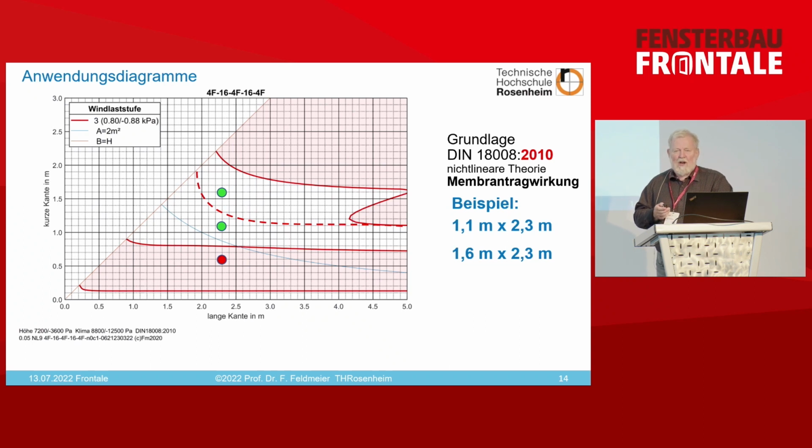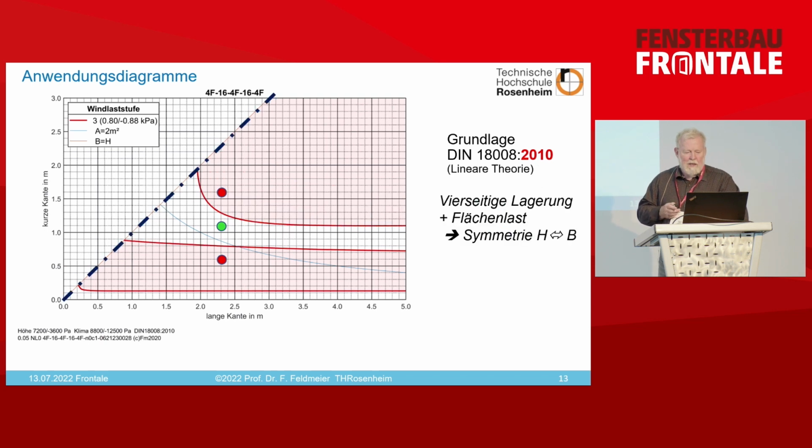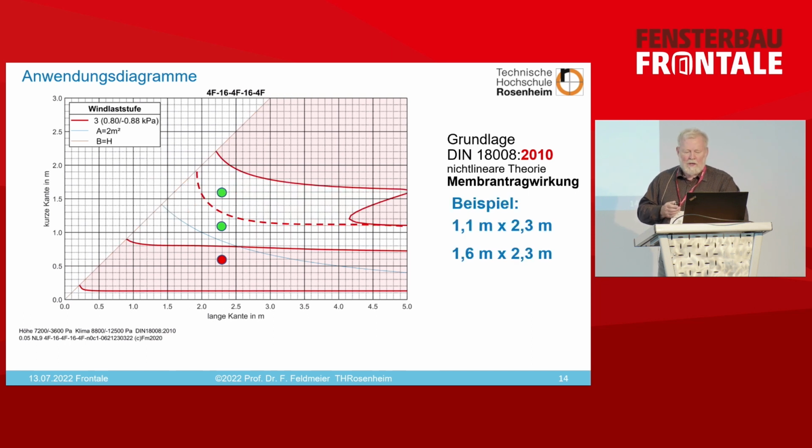So some people call the next thing a trick. Statics have improved, so static calculations have changed. And if it comes to 4 sides, up to a 1 to 2 size ratio, we have an effect that's very helpful, and that's the membrane load-bearing capacity. So this red area is now white all of a sudden, and the point is then changing from red to green. So now you can actually do it.